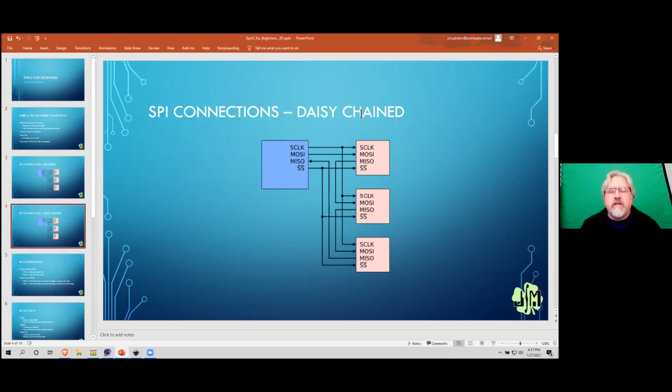It was right around 100 hertz, so not very fast in the scheme of PWM, but it was enough that it didn't cause any flickering, because these were controlling LEDs in a big lantern project that Disneyland was building for some of their hotels. But again, if you see those, they're really common parts. If you don't have them in your parts store, you ought to get some just to play with. The 74HC165 and the 74HC595. The first is input, the other is output.